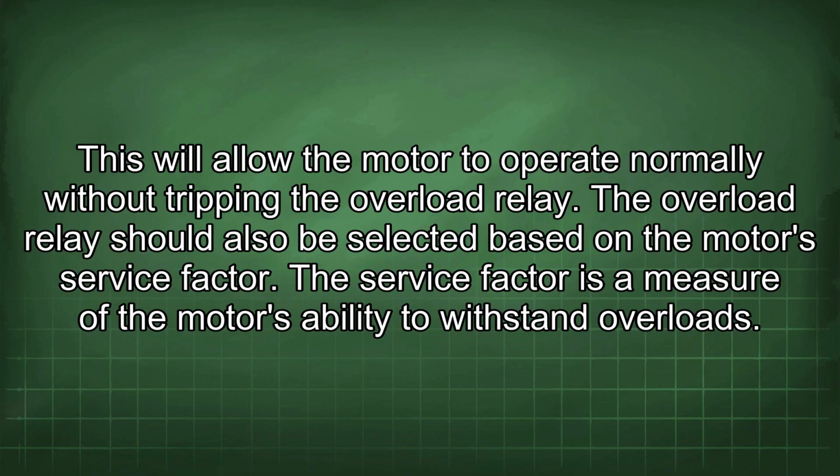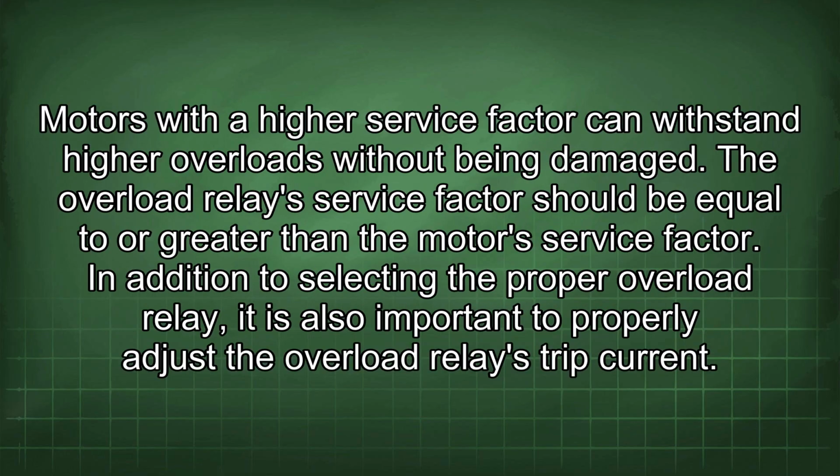The overload relay should also be selected based on the motor's service factor. The service factor is a measure of the motor's ability to withstand overloads. Motors with a higher service factor can withstand higher overloads without being damaged. The overload relay's service factor should be equal to or greater than the motor's service factor.